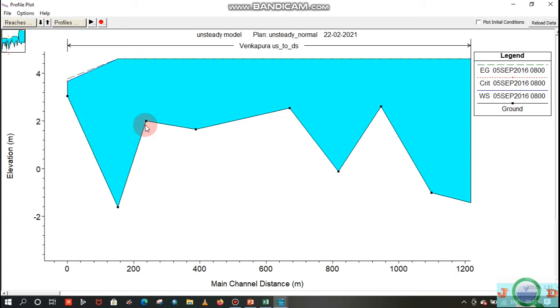The first station is on a descending gradient, and the second one is on an ascending gradient, which indicates the downstream boundary is on an adverse slope. So we can't directly use the second method, that is just taking the average of these last two cross sections. That method we can't use. We need to use the first method, that is taking the average slope of each cross section.